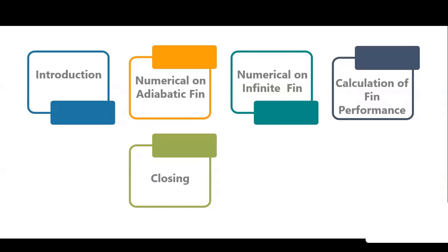One more important aspect I would like to tell you about the fins problems is that most of the data is available in the problem itself, and we already have the equations for different types of fins. So it is just the identification of which boundary condition is applicable to the given problem. Based on that, we can select a proper set of equations.